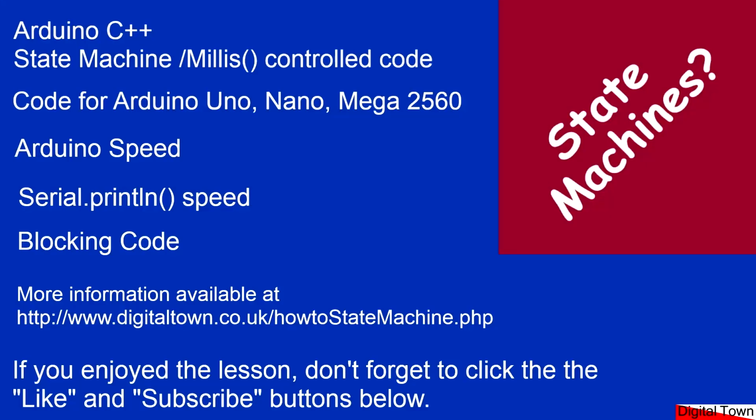I hope you remember when you're going through your code, just beware of those serial print statements, because they are going to slow it down. Beware of the dreaded delays. Beware of code that starts to go round in big loops, because again, if you've got endless loops, especially if it's got any kind of delay or serial print, you are going to add ages to your code. So that's the basics of a state machine.